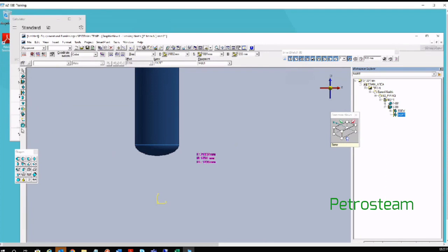This also does not have any graphics associated. It's a definition, similar to this. Click on place design solid by selecting the skirt. It has not asked you for any location. It simply placed a design solid like this, where there is no graphics and no position required.